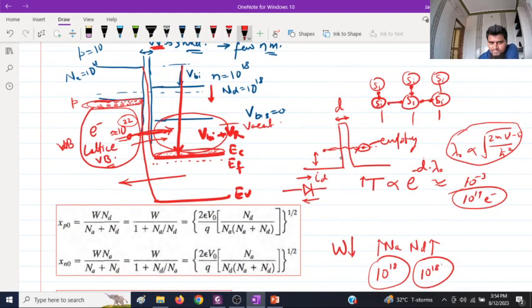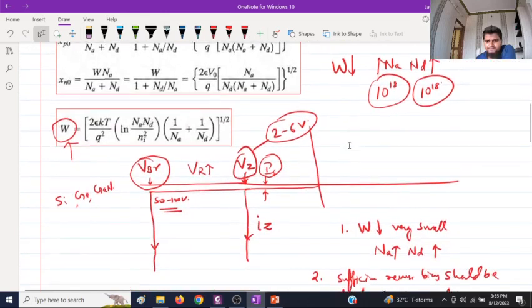So of course it should be a little more, because most of these will be occupied by P holes carriers, and some of the region in EC will be electron carriers. Even if they are aligned just like this, with these 2 points coming across, tunneling cannot happen. That is another issue that I will discuss in tunnel diodes. Of course in that case, in forward direction current will increase. Anyway, for tunneling, the condition is that it should be sufficiently reverse biased so that very high electrons in the valence band have a corresponding energy level in the conduction band of N side at the same energy states. This happens generally for VR equal to 2 to 6 volts, depending on concentration on N side and P side.